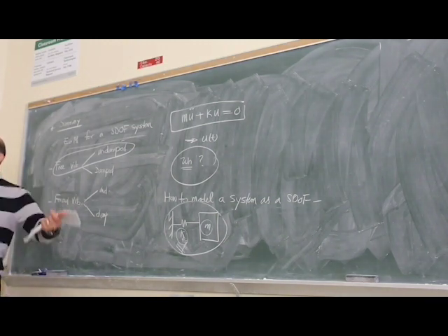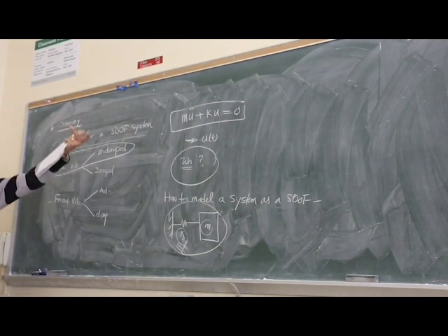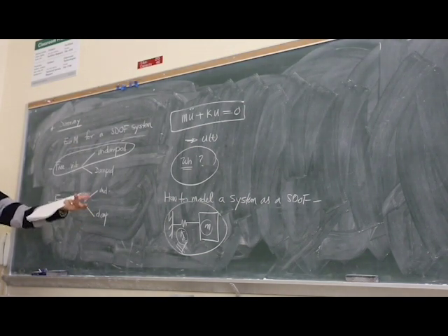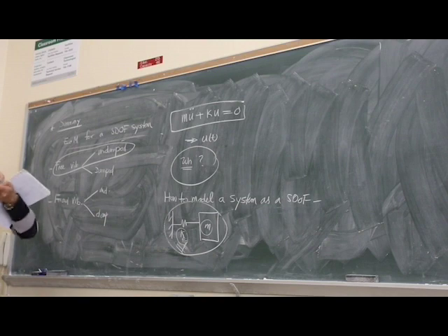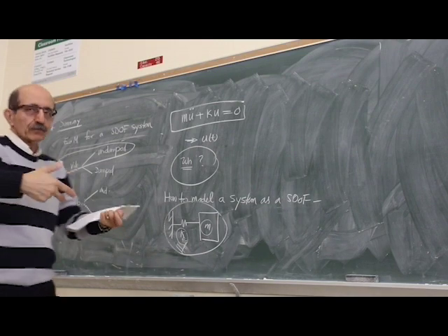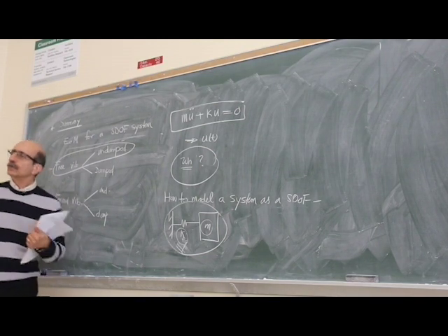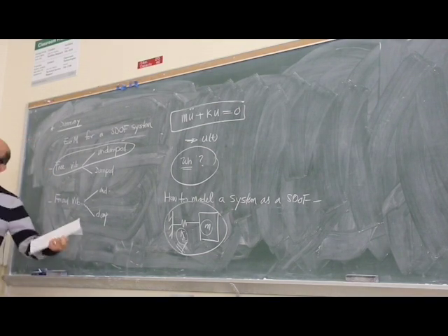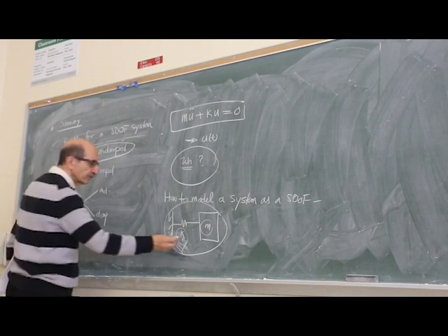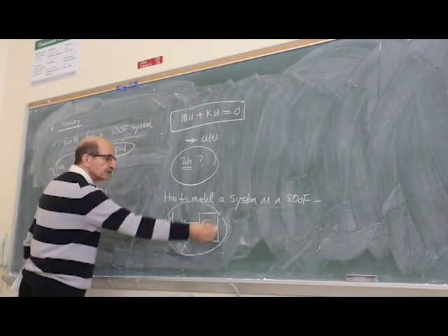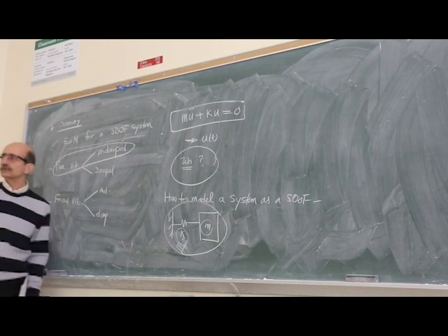You may have rotating machinery, having, say, bearings, and a lumped mass being a disc, a shaft that is basically a rotating system. Is it possible to represent the entire shaft, all these bearings, with a single stiffness element so that we can represent the system as such?